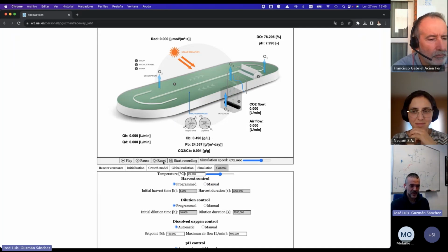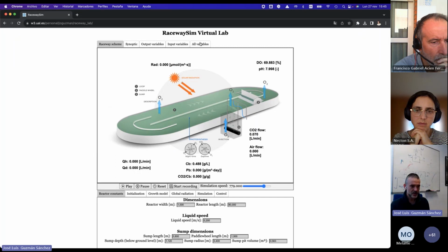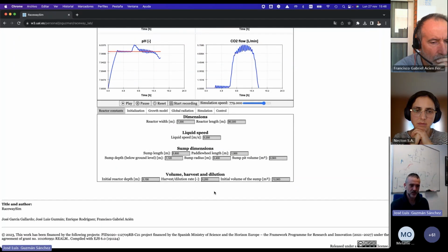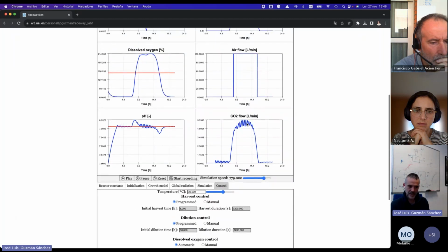And then finally, another example I can show you is regarding the consumption, depending on having a good automatic control algorithm or a classical one such as an on-off controller. I'm going to run again the default values to show you the good quality control of the pH according to a PID controller, which is defined here in these parameters. And this is the consumption. You see that we get a little bit less than 6 liters per minute.